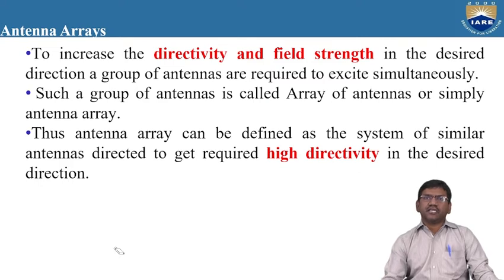The directivity of the antenna is limited. It depends upon the length of the dipole antenna and also the operating frequency range. If we want to increase the directivity, we can place a number of dipole antennas in a regular fashion, adjacent to each other, so that the directivity can be increased. Placing antennas adjacent to each other in order to increase the directivity, we call an array. An array is a group of elements arranged in a particular order, whose spacing between the elements is the same.